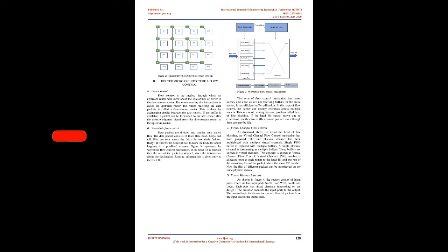There are many topologies for NOC, like chip-level integration of communicating heterogeneous elements, CLICHE, butterfly fat tree, BFT, scalable programmable integrated network, SPIN, and mesh, figure 1. Every topology has its own advantages and disadvantages. The mesh topology has the following advantages over other topologies. A. Each node is connected to 4 neighbors, except for the ones on the boundary. B. Easy to lay out on chip, regular and equal length links. C. Path diversity, many ways to get from one node to another.